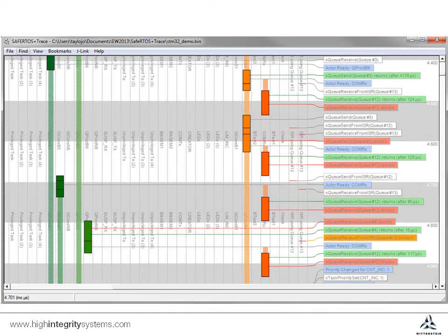At this level of zoom, each alternating grey-white bar represents 100 microseconds. The fundamental time base of the RTOS scheduler is usually 1 millisecond, and is true in this demo application too. So what we see here in this view is a very large number of context switches even within the fundamental tick of the OS. These are caused in this example every time an interrupt service routine fires, as shown on screen here, with a further context switch happening at the end of each interrupt service routine block.